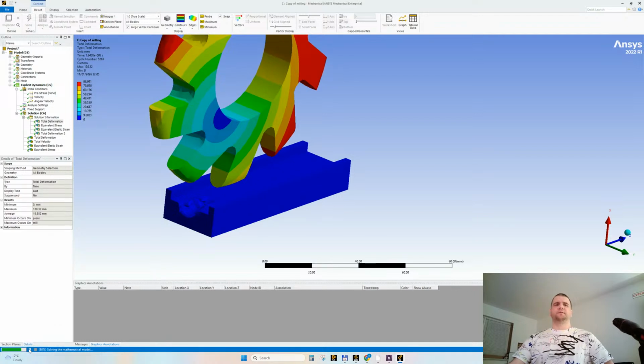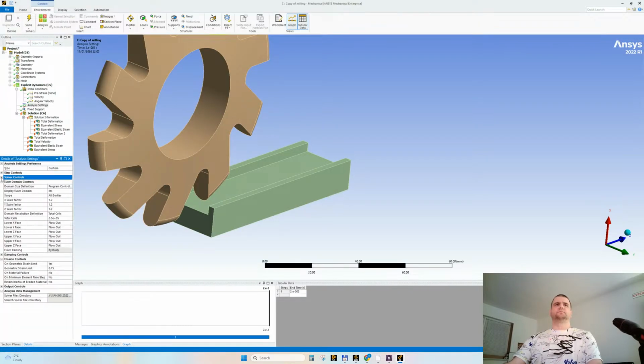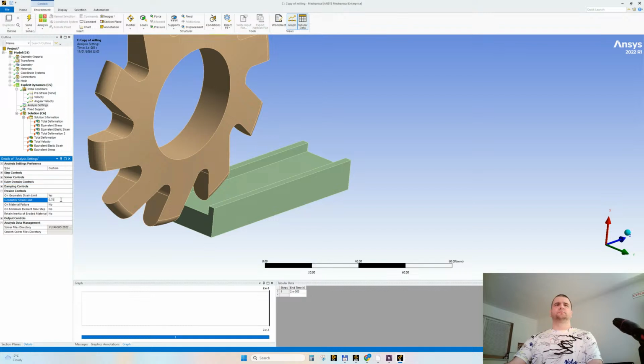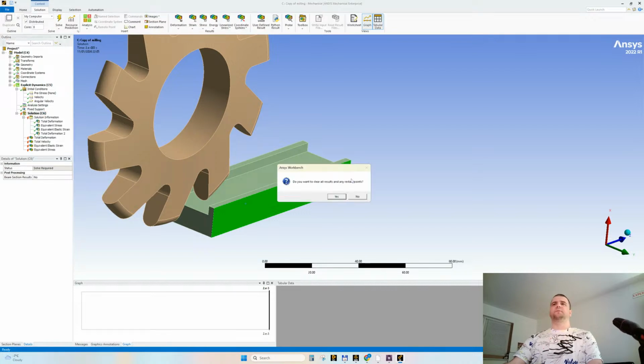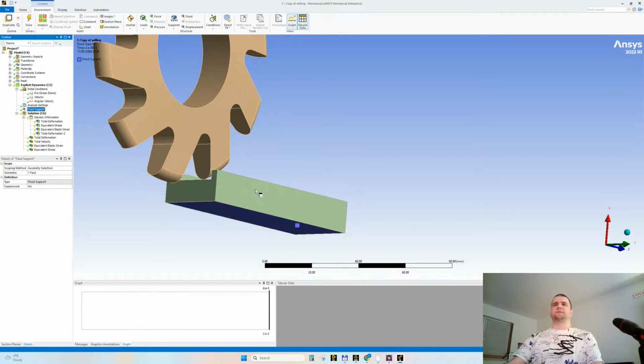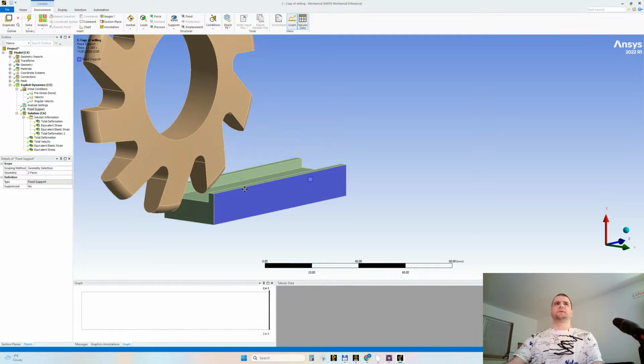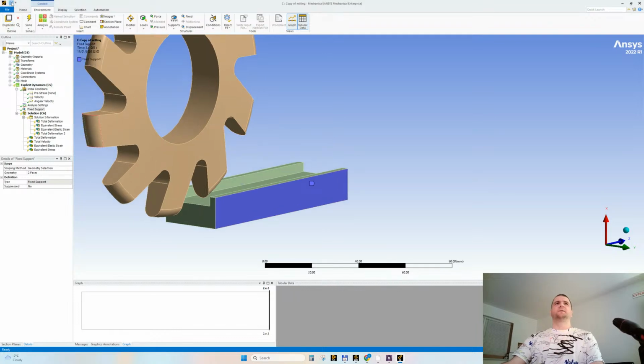Let's make the material a little softer, let's say, yes. .5 here. We give the material the possibility to be broken even faster. And let's change the fixed support to these faces and save again.